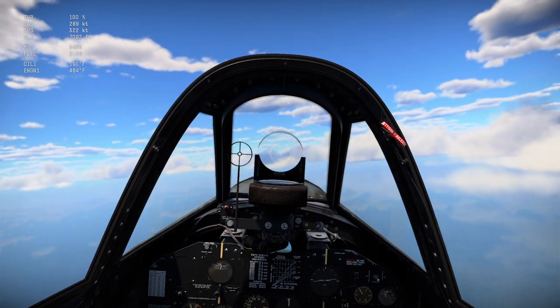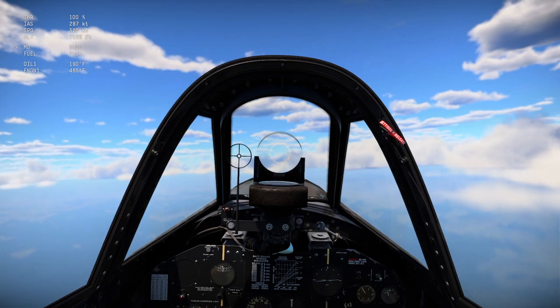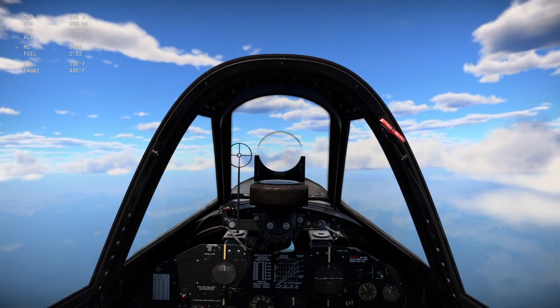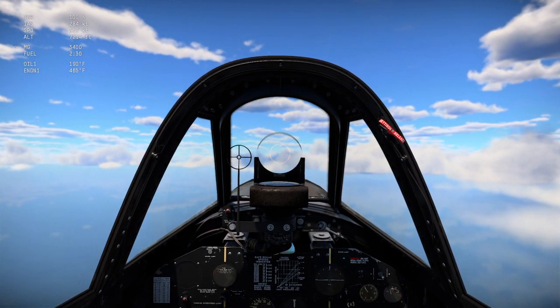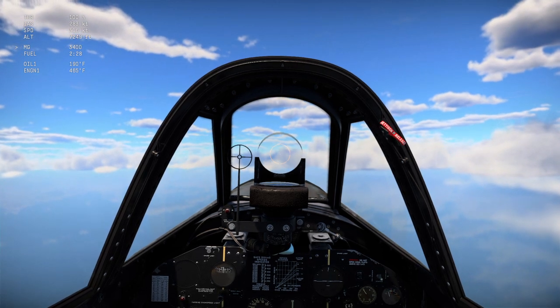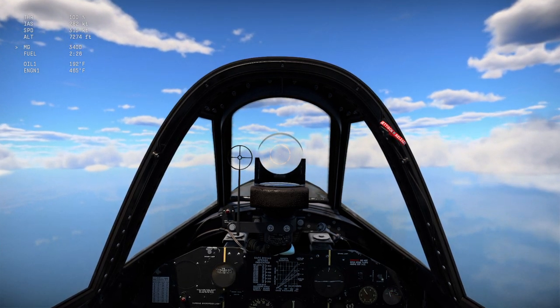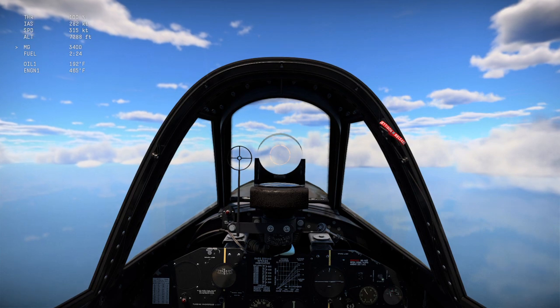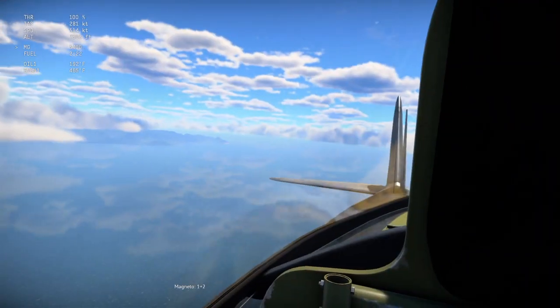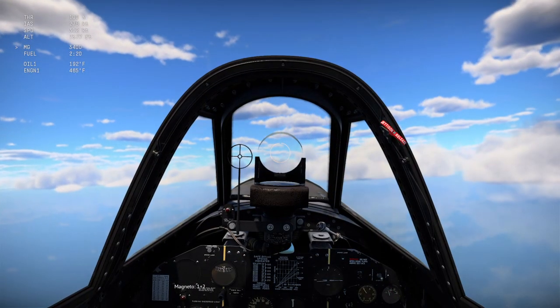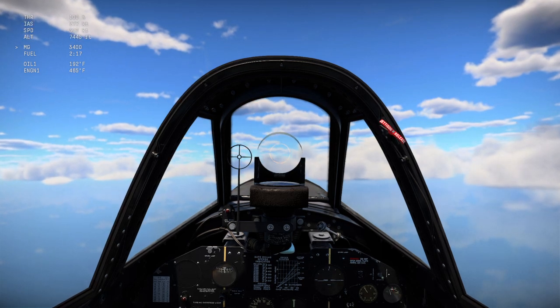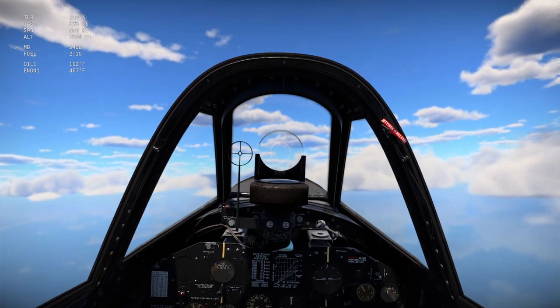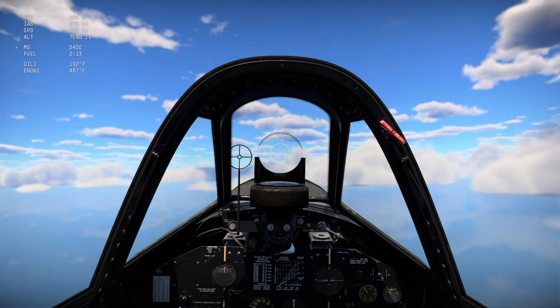So, yeah, if you're in a Soviet aircraft, run 80 when you take off. If you're in anything other than a Soviet aircraft, run 85. If you're climbing super high, go 75%, 80% to gain a little bit more power. With mixture though, mixture should be modeled by fuel consumption, not by power. And I don't know why Gaijin has it set that way, but whatever.